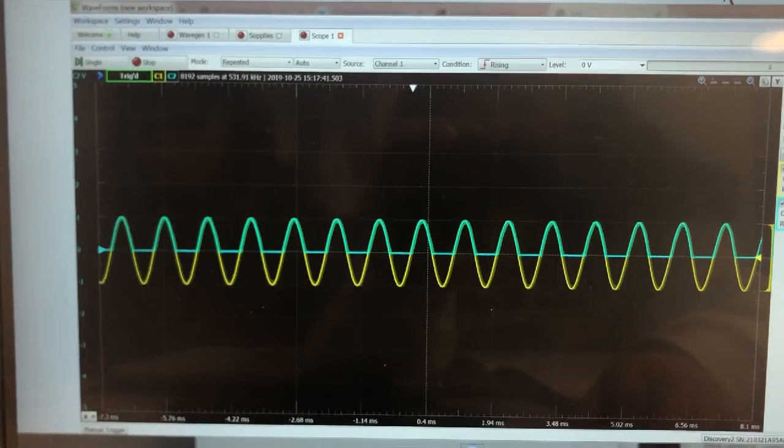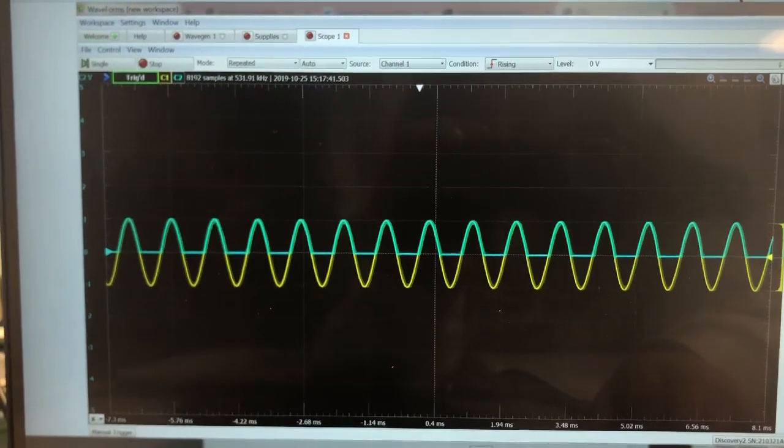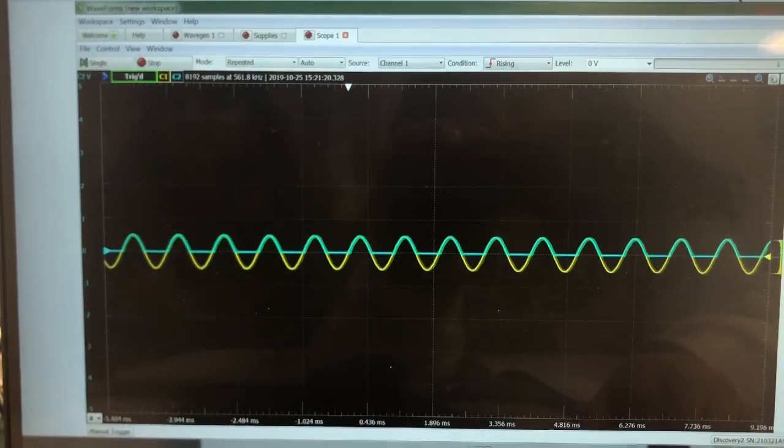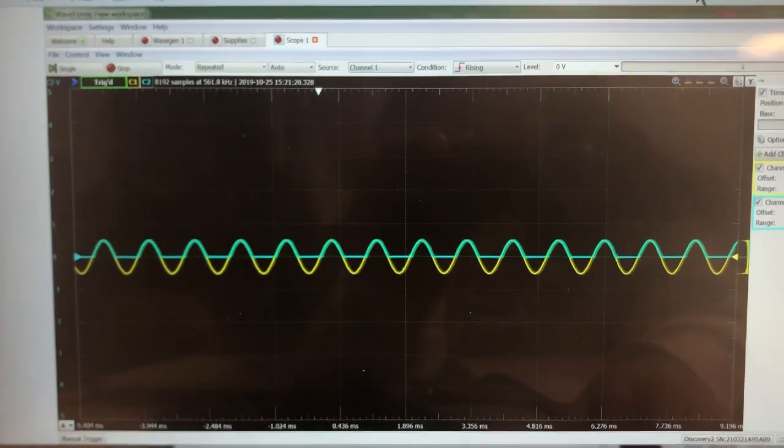And so we see that because this is an active circuit, although the input sine wave amplitude is less than V gamma, which for our diode is 0.7, the signal is still rectifying.